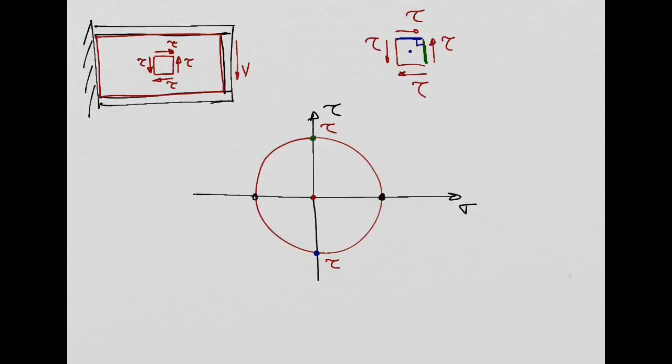This point and this point. Which points are these? Maximum and minimum direct stresses, right? Which are also known as principal stresses, yeah? So these are the highest. So this is sigma 1, this is sigma 2, sigma 3 is equal to 0. This is plane stress analysis.